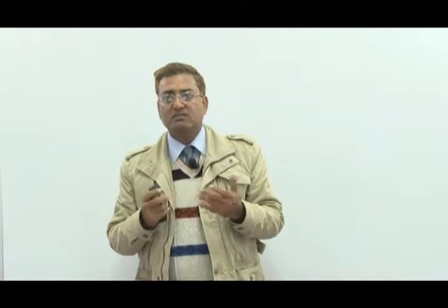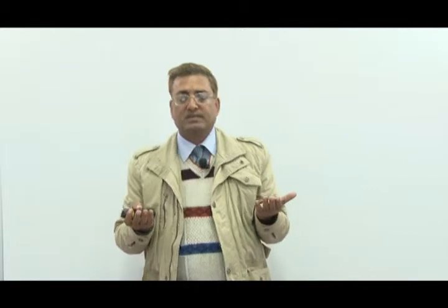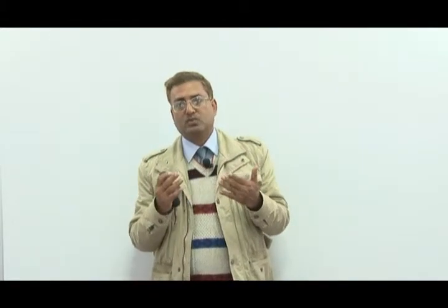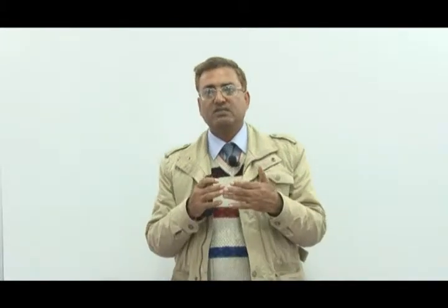So once the mapping is established from XYZ to zeta, eta and xi, the displacement field in the element can also be defined. Because it is now 3-dimensional, each node has 3 degrees of freedom, and therefore 3 displacements would occur, and let us take them as u, v and w. So the displacement field in the element can be represented in terms of shape functions Ni.